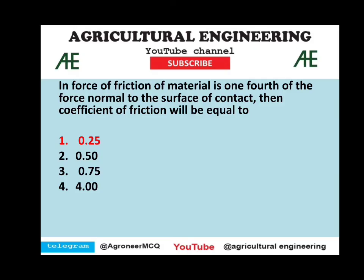If force of friction of material is 1/4 of the force normal to the surface of contact, then coefficient of friction will be, so force of friction is given by mu into N, where N is normal force and mu is coefficient of friction. So they have given value of force of friction, which is 1/4 N is equal to mu into N. So the value of mu we will get is 0.25.